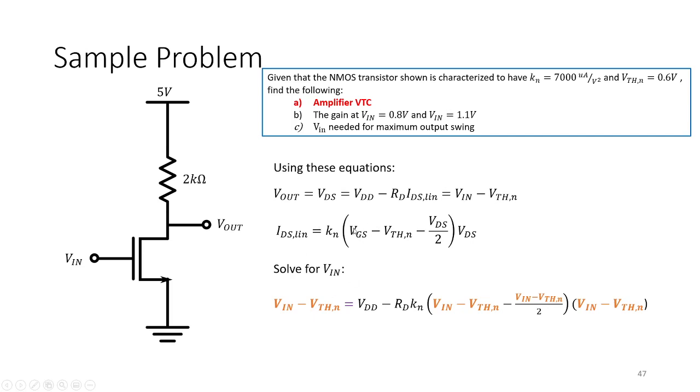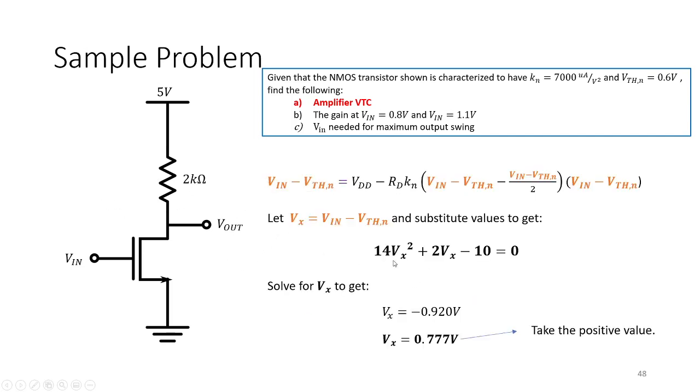So we substitute because we want Vout to be equal to VDSat, right? And then VDS is also Vout, so we want that to be VDSat, and this one too, VDSat. So we just substitute. So Vin minus VTH, so this Vin is VGS, right? So this is VDSat equals VDD minus the equation of the current times RD, which is shown here. Then we solve, we will get this equation.